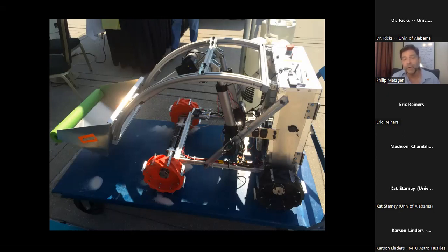Now, if you think about the center of gravity of the vehicle, if the center of gravity is near the cross point of those four wheels, draw the two diagonal lines. If the center of gravity is near the center of that X, and you've now got a hole under one wheel, it doesn't take a lot of upward force from the diagonally opposite wheel to push it up a little bit so the vehicle rotates on that diagonal.